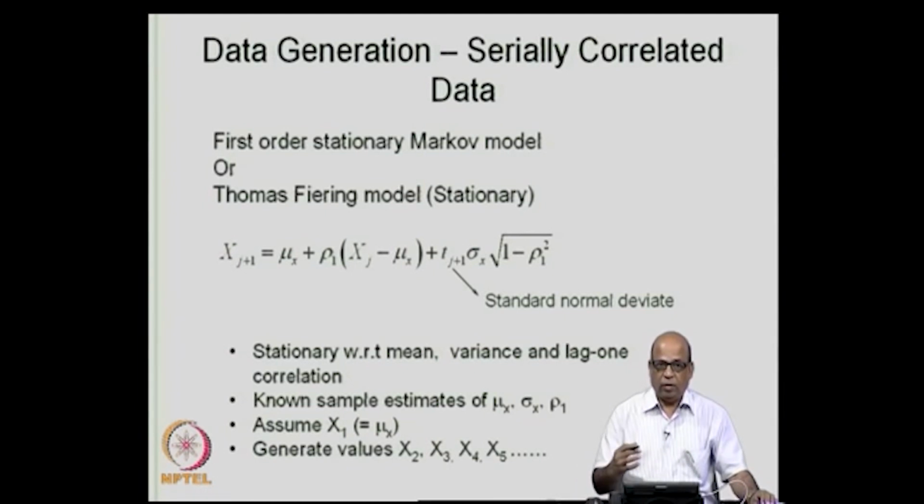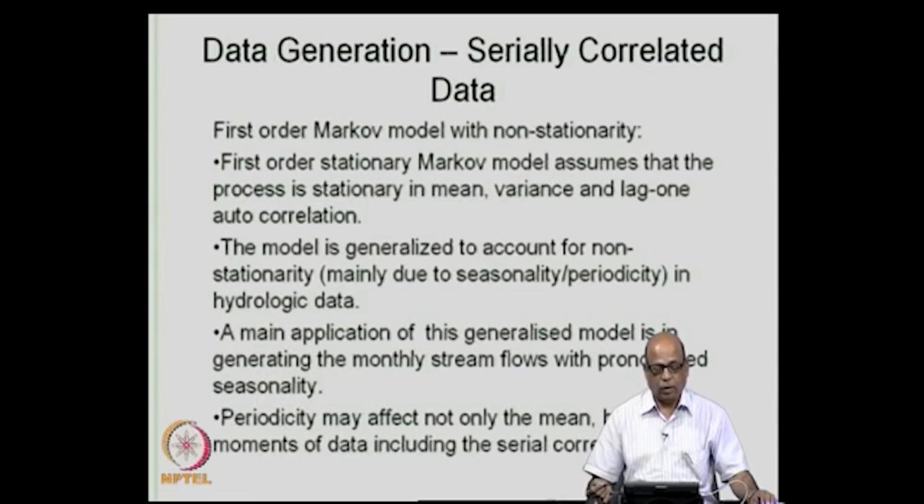They can be monsoon, non-monsoon season, in which we will have 2 seasons, or monsoon, summer and winter, 3 seasons. We may consider 10-day durations, in which case we may have 36 or 37 time periods according to how we discretize. Like this, we will now consider the intra-year periods over which we are interested in generating the flows.